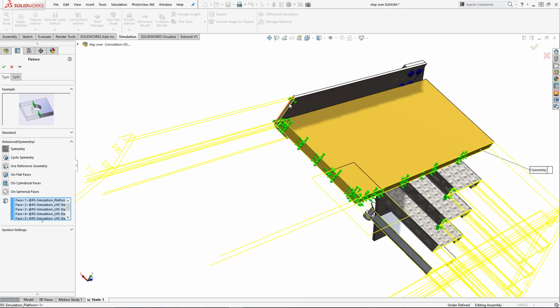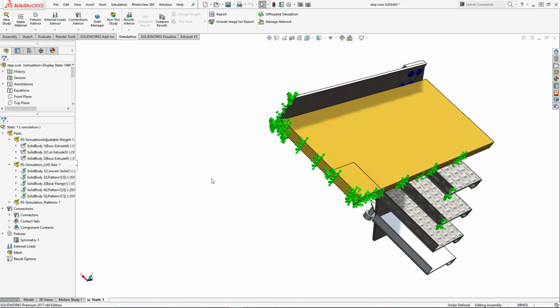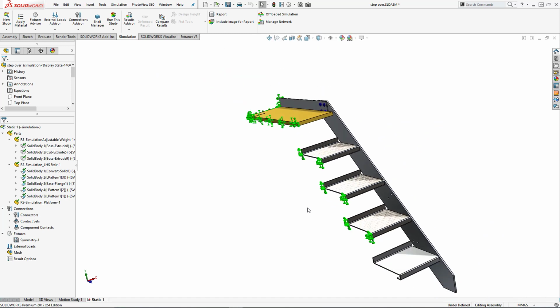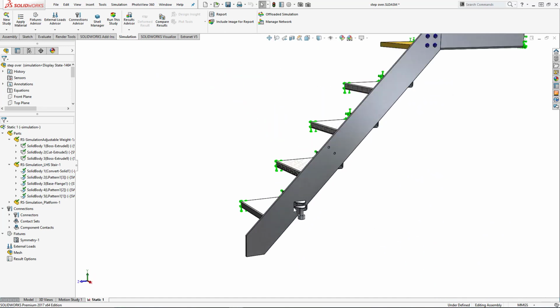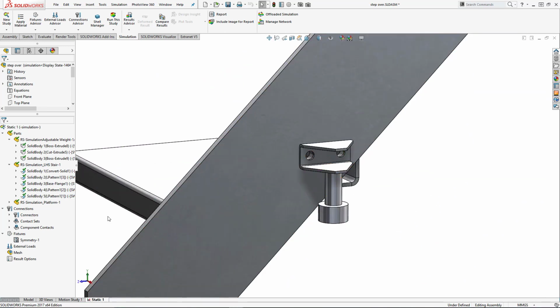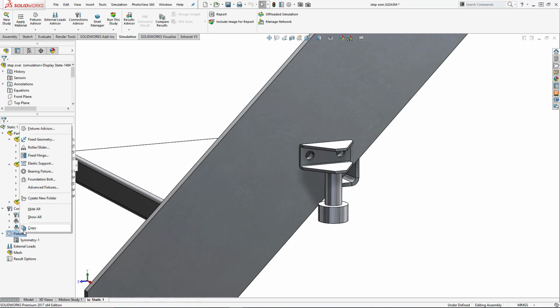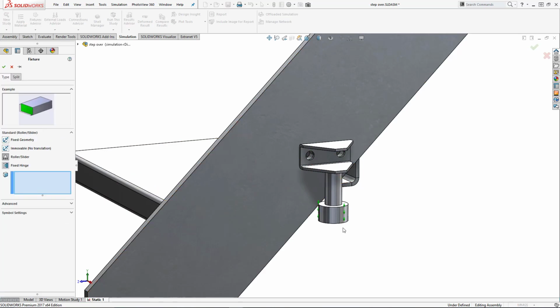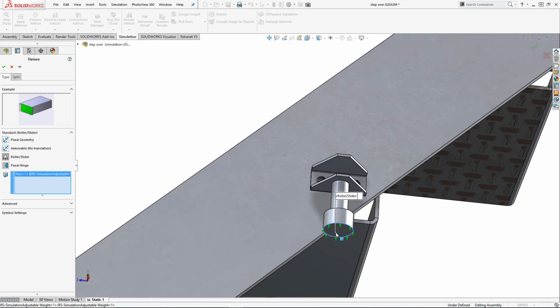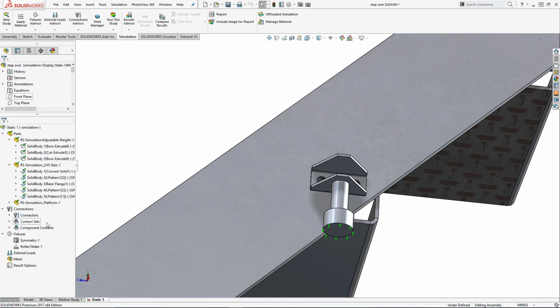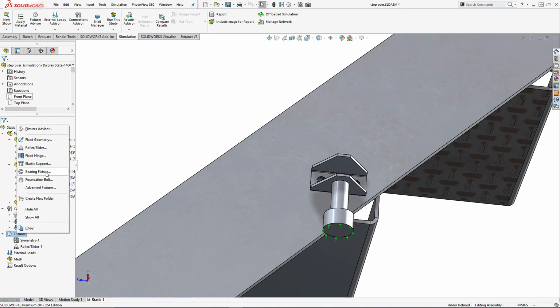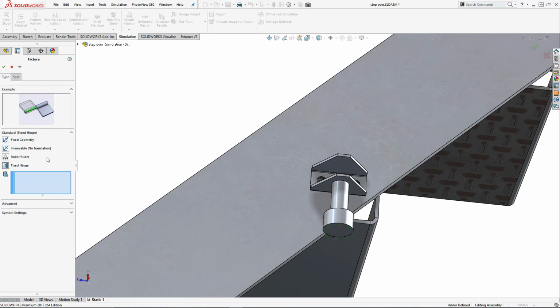You can see from the preview there, this is how it's going to expand the solution out to take into account the fact that it's a complete set of stairs. But then what's stopping it from moving around? Well, that's where that foot plate was mounted. So I've got a couple of the components left over, but effectively the foot doesn't really move. So I'm going to stick it on here as what's called a rolling slider. So that face can move around, but it can't go further down.